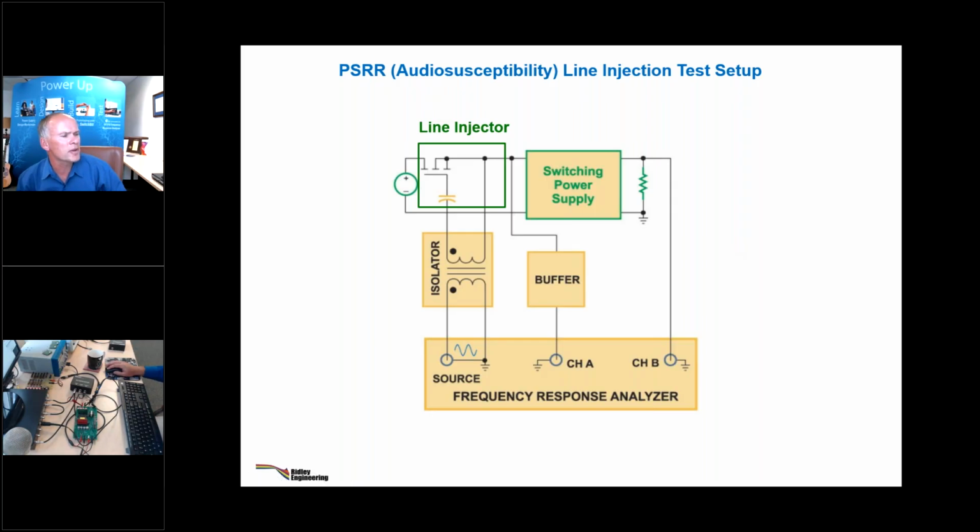Could you do this method with a function generator and a scope like you did many years ago on the freq source? Yeah, you can, but you've got to have some power. So what I did many years ago, I think you might remember, I added an amplifier to it. I got a vacuum tube amplifier that had about 150 kilohertz bandwidth, and then I could drive some real current in there. And you could do the same thing in here.